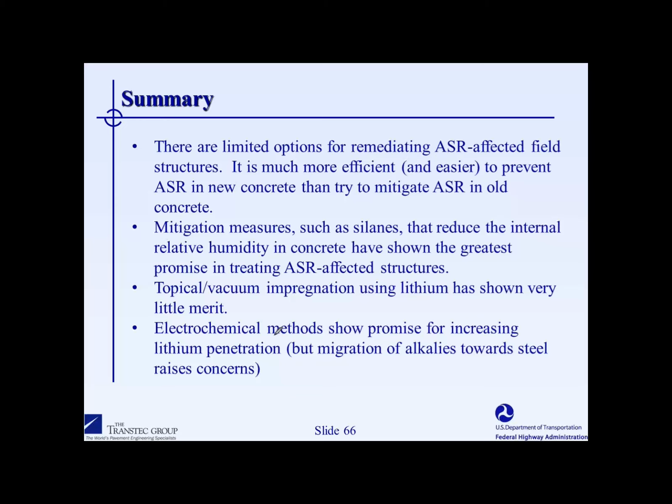I think that the key thing there is whatever technology will reduce the relative humidity below 80% should work well with regard to reducing ASR. And as part of the study with integral water repellents, we are measuring the relative humidity throughout the course of the trial.